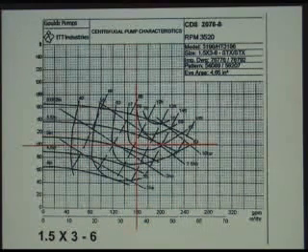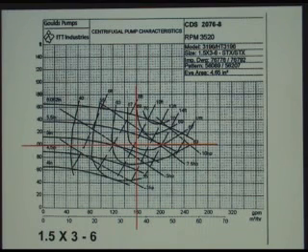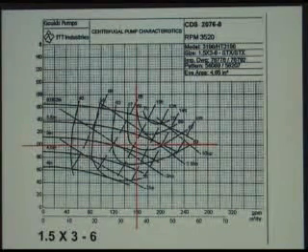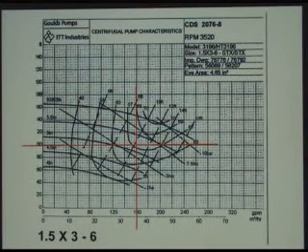You'll notice the efficiency curve shows that this pump would operate at about 67% efficiency, about 67.25. But the NPSH required is 10 foot. So we couldn't use this pump selection for this application because it exceeds the NPSH by over 4 feet.